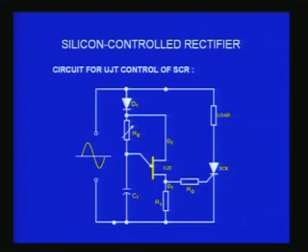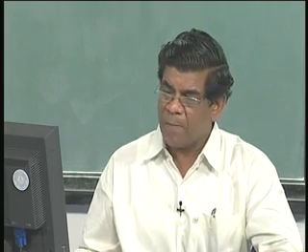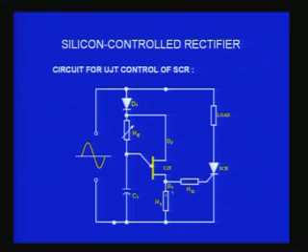Lastly, we already studied about UJT. One of the very important applications of UJT is to apply control pulses on the gate of the SCR. So I can combine a UJT and an SCR like in the circuit shown with an RC network, right. I take the rectified output and connect it to the B2 and B1, and I put a resistance through an RC network and connect the gate to the emitter of the UJT to this. Therefore, depending upon the pulse, the eta VBB plus VD will be reached here, and therefore that will discharge the capacitor. Therefore I will get a pulse here.